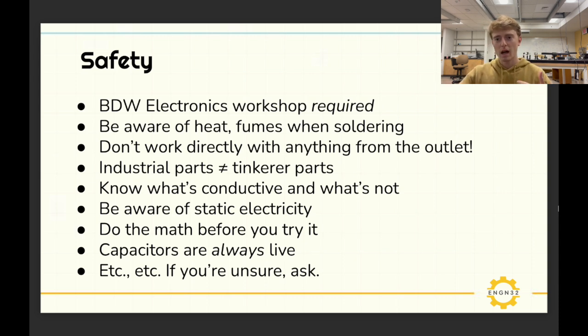Shocks and static discharges can be thousands of volts, 10,000 volts, and that can seriously destroy a part if you manage to shock it. This is especially important as we move into winter, because people are going to be wearing more clothing, and that's going to create static. Unfortunately, we don't have wristbands to plug into the lab benches here, and so you're just going to have to be as careful as you can.